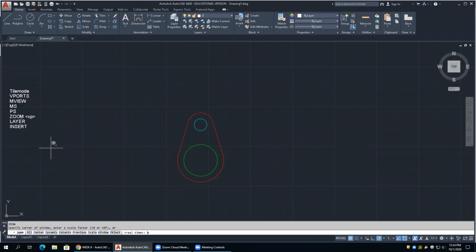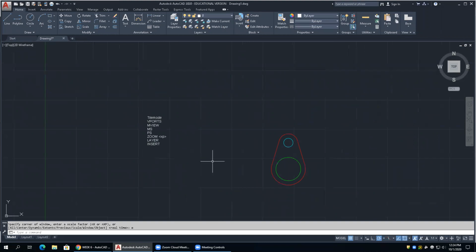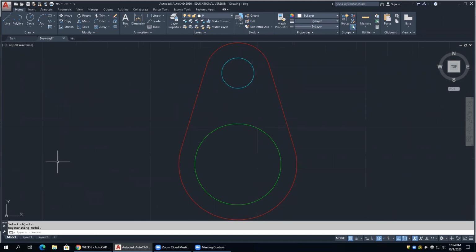All right. So if we have a part like this, the old way of drawing in AutoCAD prior to this concept of paper space, model space, you didn't have paper space, just model space. So when you plotted, if you're drawing full scale, you have to do a scale factor when you plot, like we've been doing.